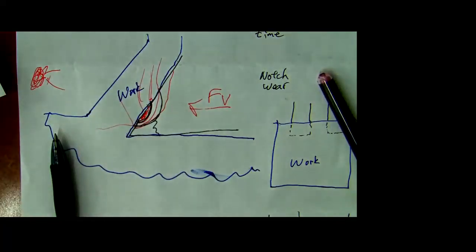Aluminum conducts the heat like crazy. If you have good tungsten carbide cutting tools now, I find it hard to cut too fast because you can go to town because it's real good. What's the problem with titanium? I told you this earlier. The problem with titanium is there's no thermal diffusivity. The heat does not go into the chip or the workpiece. The heat just sits there and softens your cutting tool. And this is why it's so difficult to manufacture with titanium.